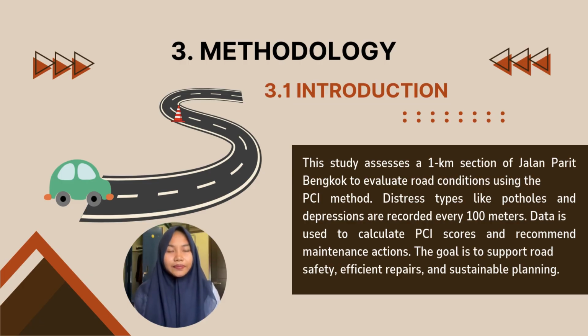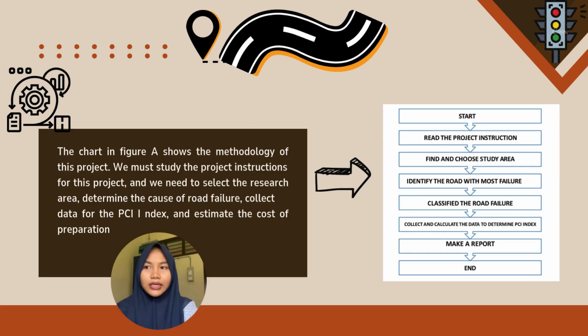And methodology. The study assesses a 1 kilometer section of Jalan Parit Bengkok to evaluate road condition using the PCI method. Distress types like potholes and depression are recorded every 100 meters. Data is used to calculate the PCI score and recommend maintenance action. The goal is to support road safety, efficient repair, and sustainable planning. The chart in Figure A shows the methodology of this project.